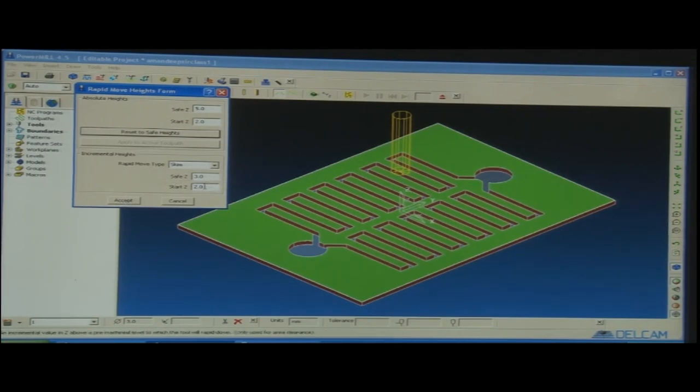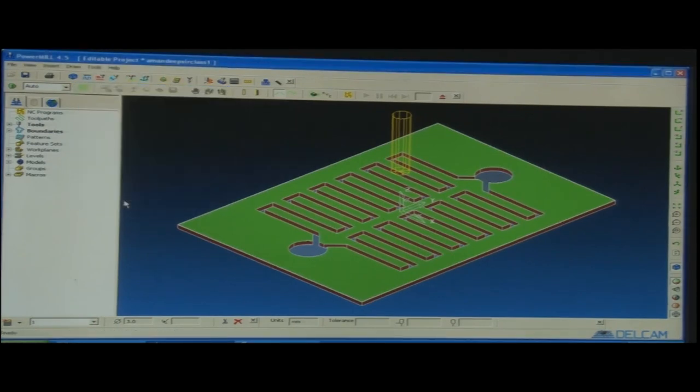It will then go down in 2 steps, 3 mm and 2 mm, when the actual cutting feed is given. So, this is a safe working height when the tool tries to enter the job from the top of the block. Sometimes the top surface is not flat or some roughness is there, like I just showed you with the mouse. If it has some surface, there has to be some safe height, and that is already evaluated before we start the machining.